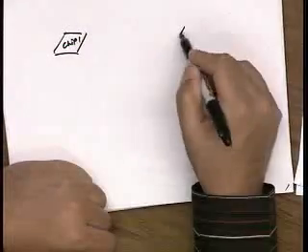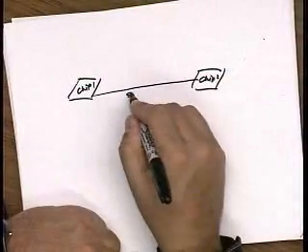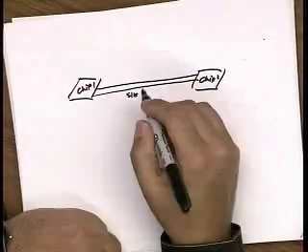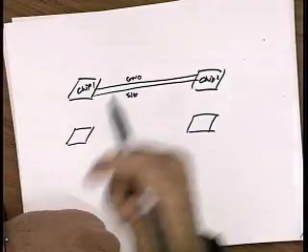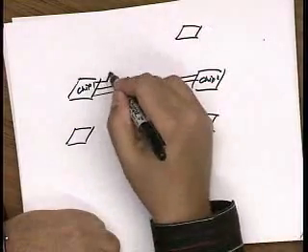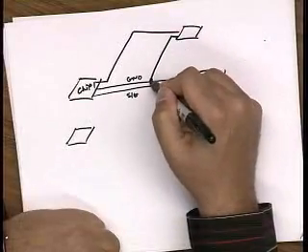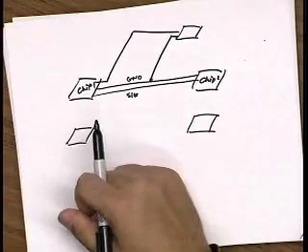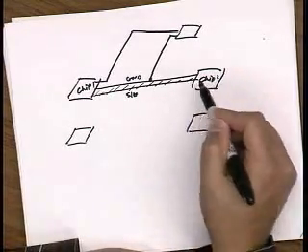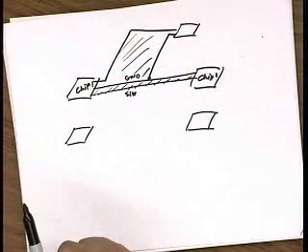So let me maybe draw a picture and make it a little more clear. So I have kind of a chip 1 here and a chip 2. And I have a couple of options. One, I can route signal and ground together like this. Or I could route... And, let's say that, okay, that's fine, but let's say now I have something like this. And let's say that I decide to use the same ground because my board is kind of messy. I don't have a place. Well, obviously this is a bad idea, right? Because this is fine, right? This has a small cross section and it picks up little noise, but this loop now has a huge cross section and it can pick up noise. Besides noise, what else should I be concerned about?